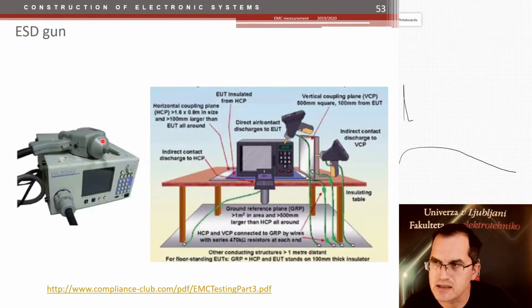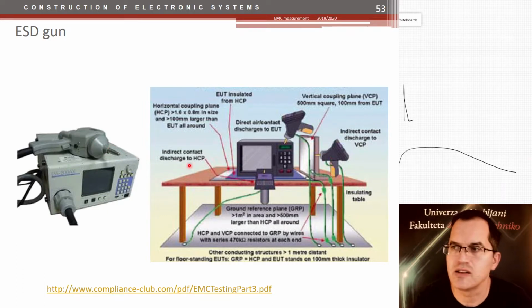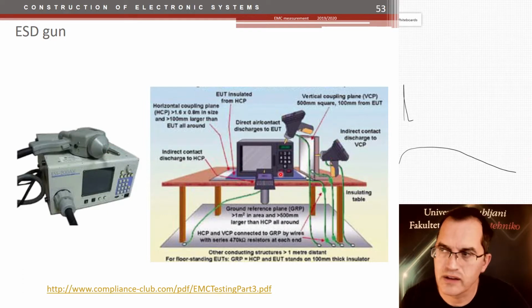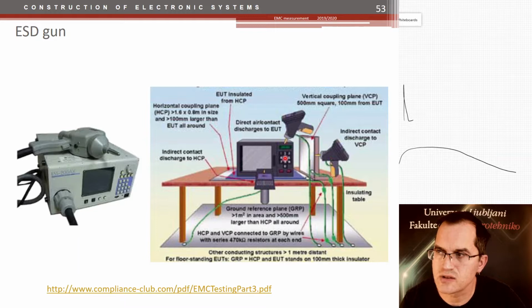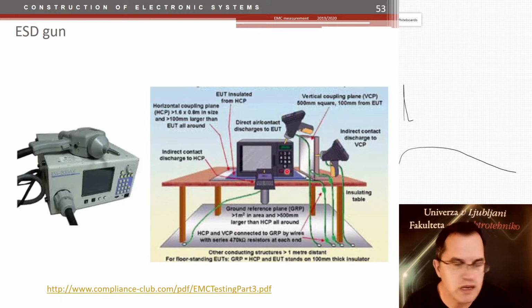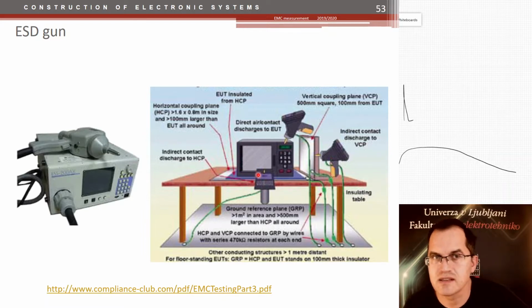And this tip has the size of a human finger. And actually what you do, you stick that human finger anywhere on the device under test when you can. You stick it to the connectors, to the keys, to every opening, whenever you can. Connectors are the most harmful, I would say, then display and so on. And if the device stops working, that's a failure. If it resets and doesn't start again, it's a failure.